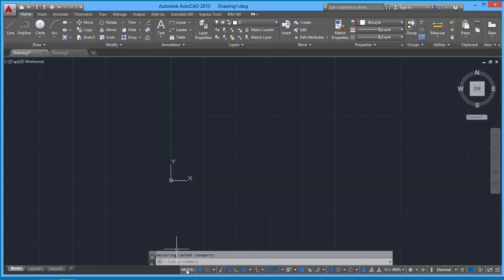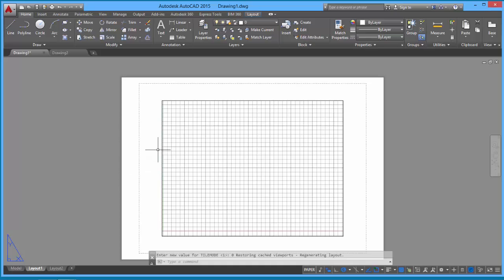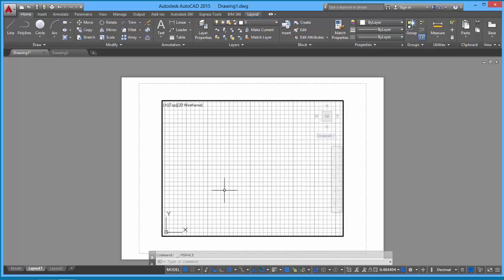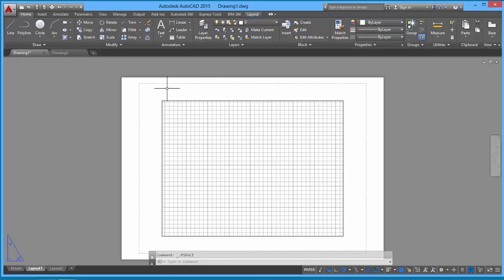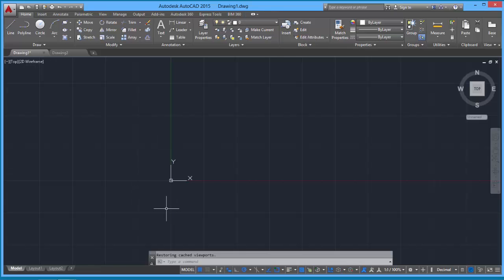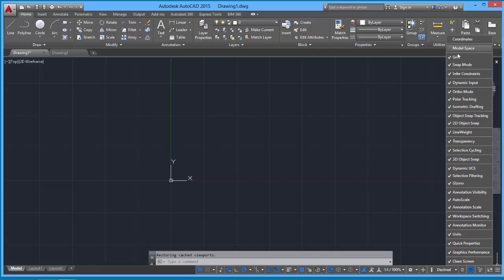But anyway, this thing, if I turn this on and click on model space, it takes me over to layout space. Now if I click on this one, paper, you'd think that it would take you back to model space, but it doesn't. It takes you through the viewport into model space, but doesn't actually get you back to this tab. So what you have to do is click on that to turn off the viewport. You can access it by double clicking as well. Double click away from it, deselects, and then back to model space. So you can keep that on, turn it off, but I'm going to close these down as I go through. So that's model space dealt with.